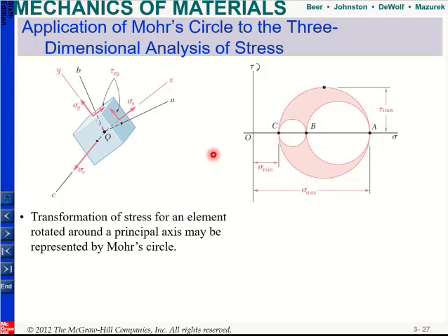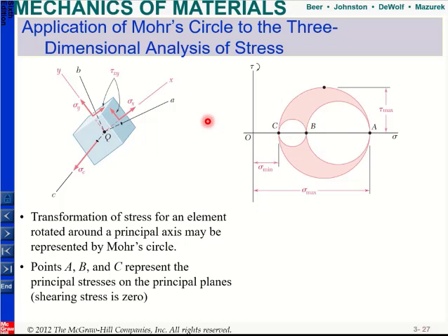Which means that if we use our Mohr circle in 3D, instead of getting one Mohr circle, we will get these 3 circles. So between each axis, I can get these 3 stresses. And similarly, since this is my normal stress and this is my shear stress, what you will see here is that when I find my principal stresses, they don't have any shear stress.